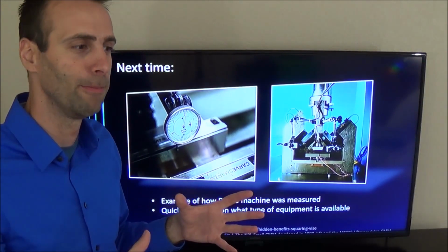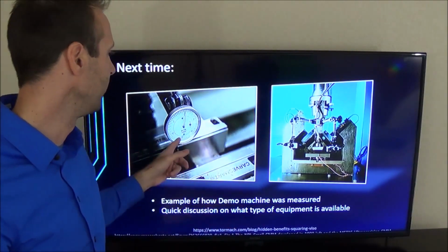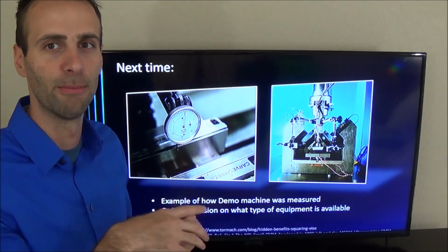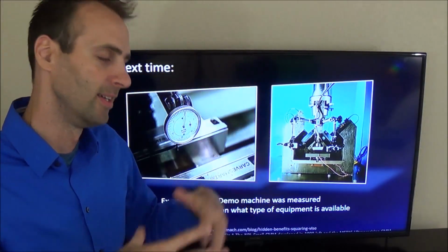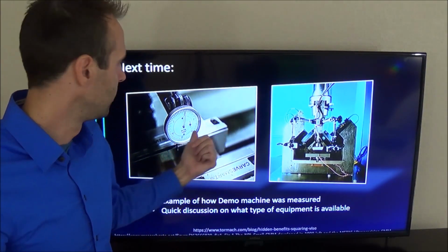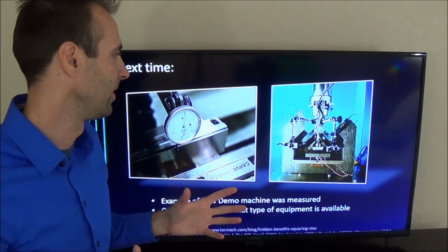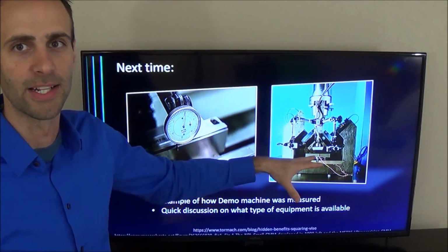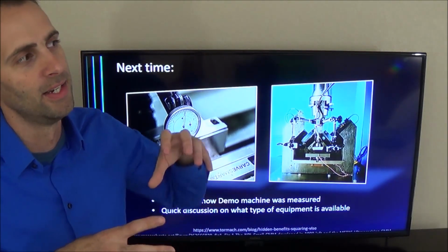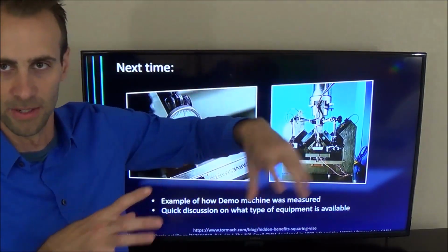But for the 3D printing people, on a machine that's made out of rubber and plastic, you want to calibrate that every single time you turn it on, and this is more than enough, right? You can even build a one-button auto calibration that'll just do all that in a minute or two minutes or five minutes or whatever. So you don't need crazy expensive tools, and with reversal techniques we can minimize some of that error. But keep in mind that a lot of that stuff really does exist, and there are lasers that you bolt to the table and align to one axis, and it'll measure all 6 degrees of freedom as you're going through each of your moves, right?